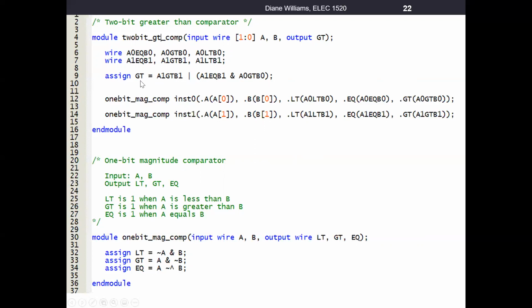And that's how we use other Verilog modules, instances of those modules. We call this module instantiation. We use an instance of this other Verilog module that we created. We use 2 instances to structurally build a 2-bit greater than comparator. You will likely do something with this in your homework with the less than circuit.